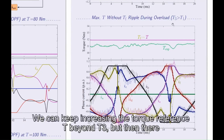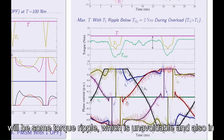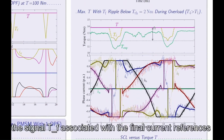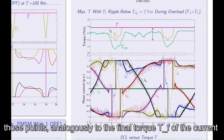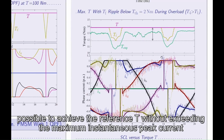We can keep increasing the torque reference beyond T3, but then there will be some torque ripple, which is unavoidable. Also in the signal TF associated with the final current references. And also the experimental torque shows some higher ripple at those points, analogously to the final torque TF of the current references. And this is because at those times it is no longer possible to achieve the torque reference without exceeding the instantaneous peak current in some phases.